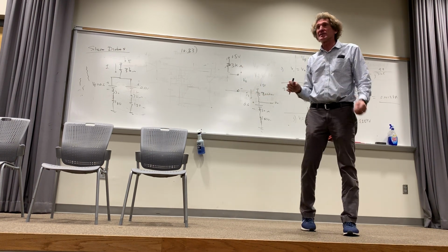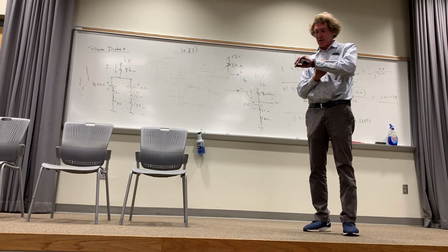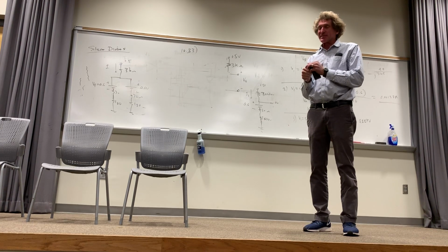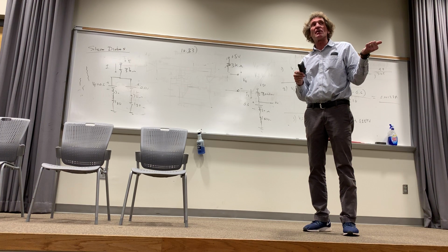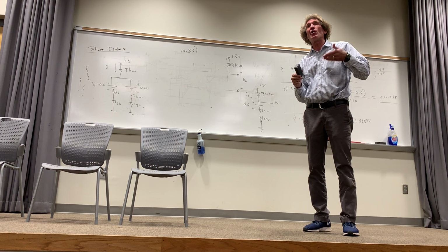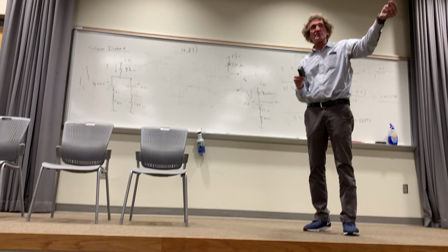This is a common way to start seeing things easily with diode problems. That's a simple problem, and I get it. I was going to do the equations and go through them, but this is probably better. Remember, you're going to have an on resistance when it's conducting, and you're going to have to overcome a forward voltage. That's the model we use.